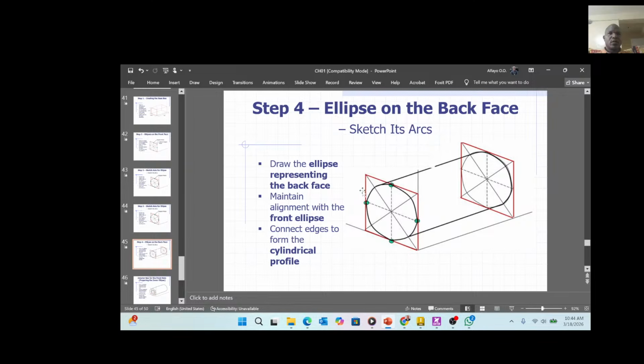And again, trace this. Remember, a point of symmetry can be traced. For example, at this point, you can bring a pair of compass from this edge and that edge, borrow this length from here, and take your pair of compass to that span radius. Or from this point, you can draw a parallel line to this one, that edge. And upon getting this length, because you don't need to draw the entire of this, pay attention to what I'm just saying.